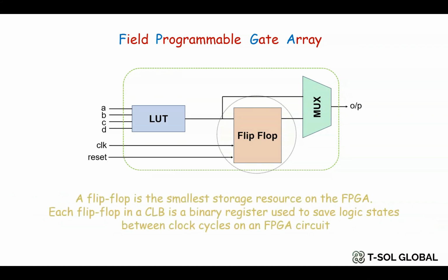Next, flip-flops are binary shift registers used to synchronize logic and save logic states between clock cycles within an FPGA circuit. On every clock edge, a flip-flop latches the 1 or 0 value on its input and holds that value constant until the next clock edge.